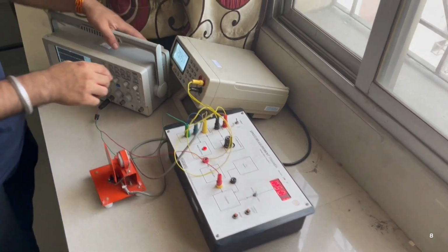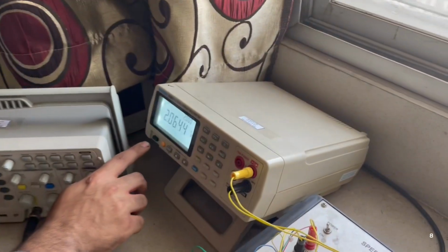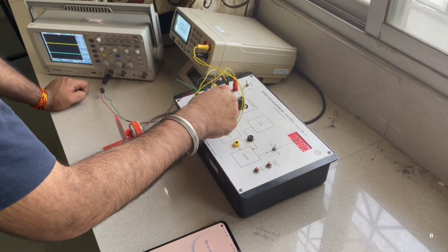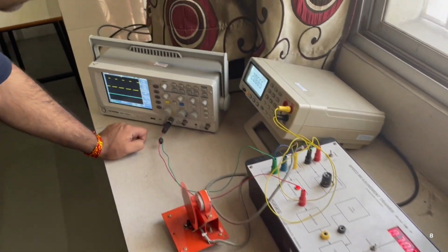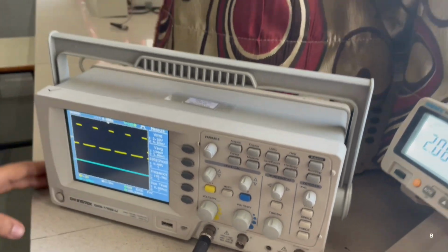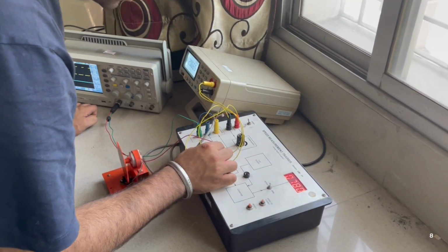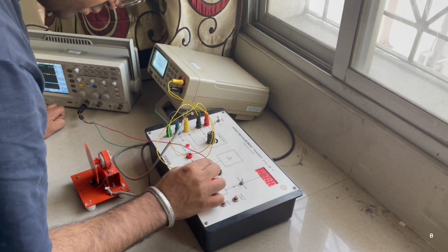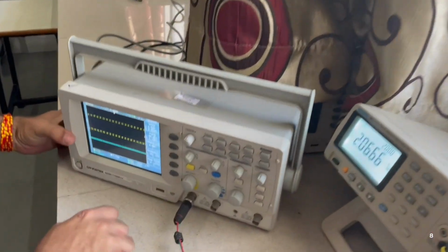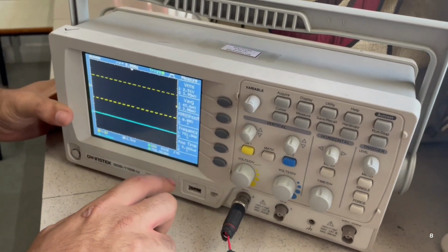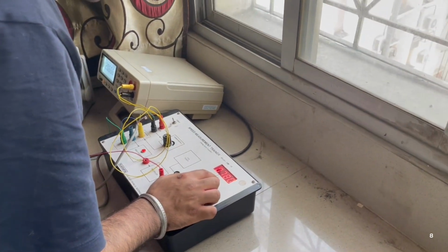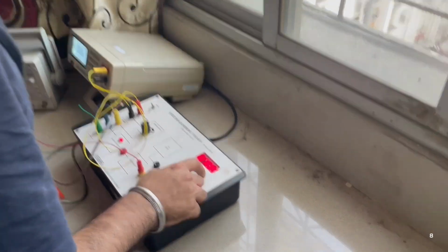First we increase the voltage of the motor and measure the voltage across the terminals of the motor using the digital multimeter. Now we will insert the pin after the wave shaper and measure our frequency using the cathode ray oscilloscope. Then insert the pin after the 4x multiplier, measure the frequency again, and we will also note the RPM using the display on the trainer kit.